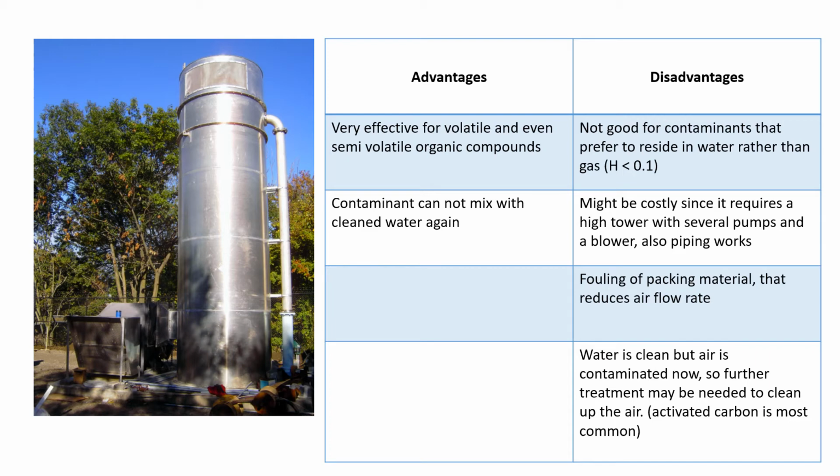Despite air stripping's high removal rate for volatile organics, the hydrophilic chemicals and inorganic compounds are not the best candidates for this method, since it's ineffective for them. Because this treatment method consists of several different equipments like a long tower, which is generally between 5 to 12 meters, pumps, air blower, and packing materials, it might be more costly than other water treatment techniques.